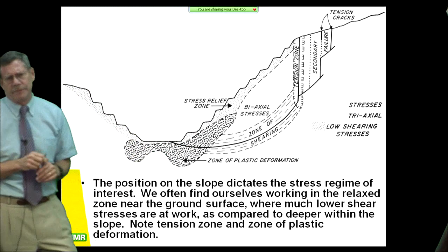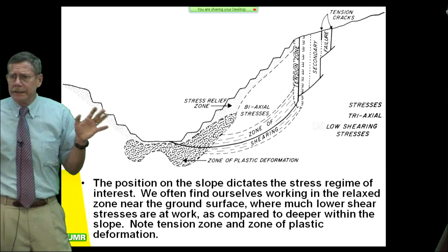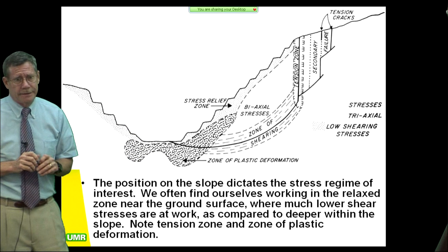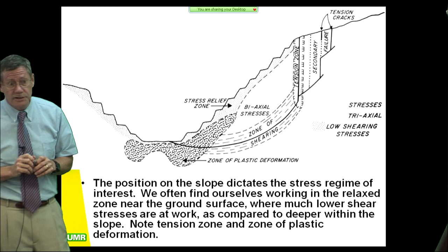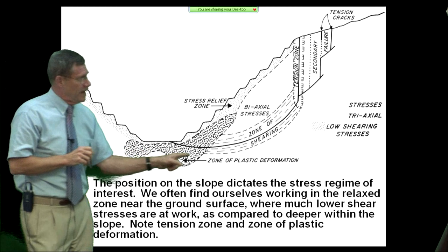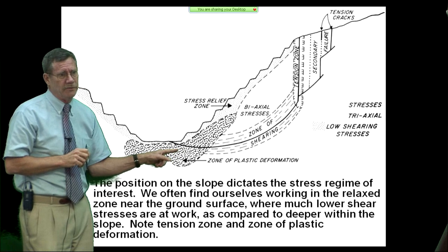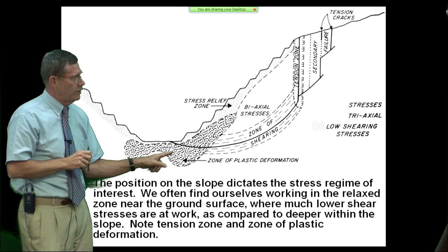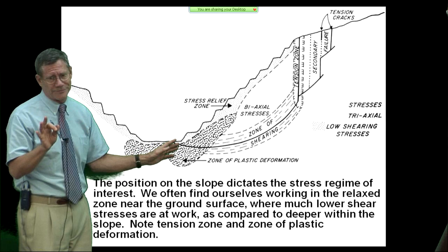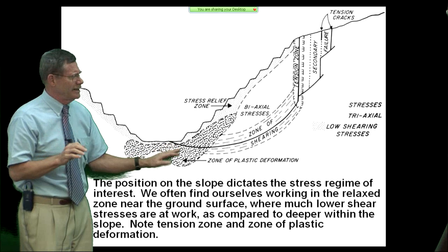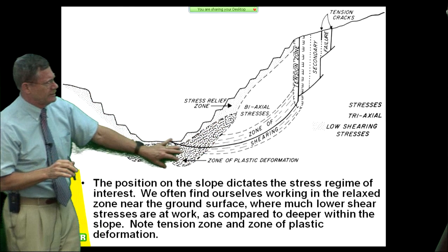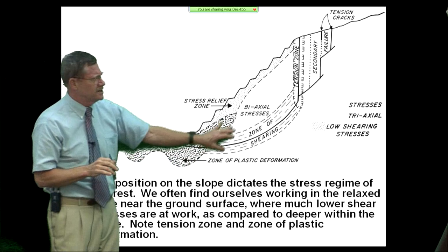It's moving all over the place. And they're saying, what can I do? Not much. Not much you can do down in here, because your pipeline in this zone is going to get tweaked. It's going to get moving around. You come in here and dig a big hole, you're just going to make everything worse. So that's not a great idea. So you don't have a lot of options down in here. You're in the passive resistance zone.